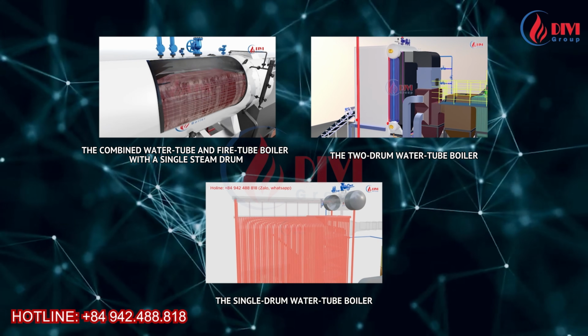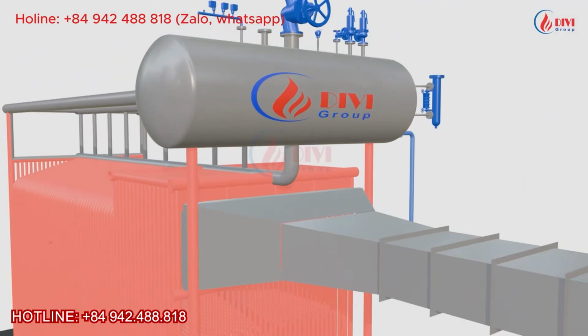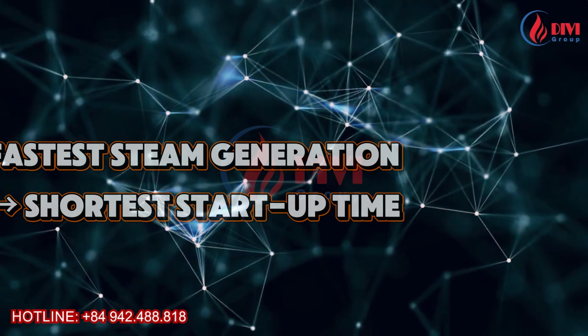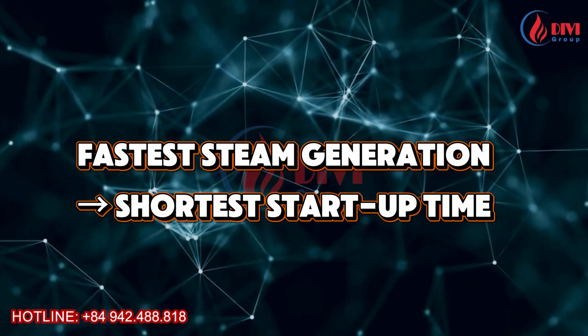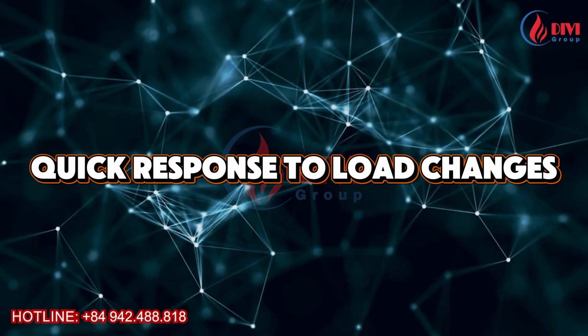Finally, let's look at the single-drum water tube boiler. Among the three designs we've discussed, the single-drum water tube boiler contains the least amount of water. Because of its lower water volume, it offers the fastest steam generation. It also has the shortest startup time. This makes it an excellent choice for applications where the steam load changes rapidly.